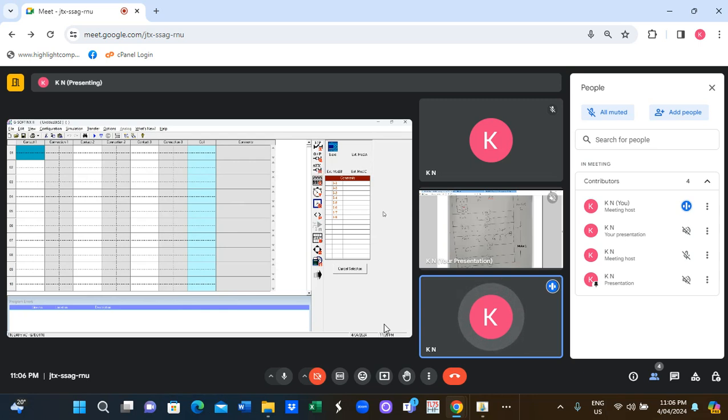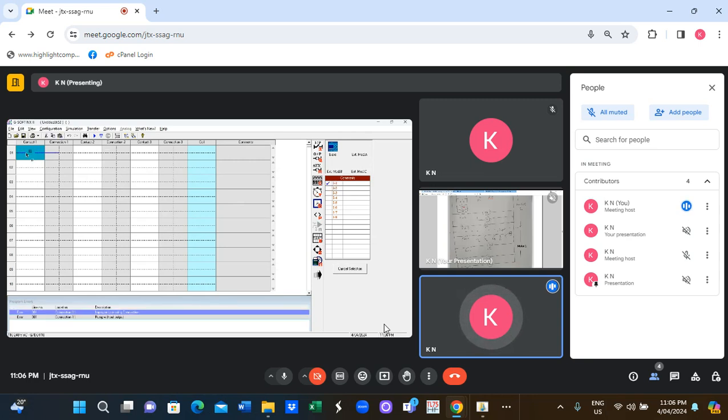So firstly I will put this on input. You press the input. Here I1 is a normally open contact to start the motor switch. I draw the wire and I insert it. So this is I1, you can see. I1 tells us it is normally open, so you can see the capital I1. This is normally open. Small i1 is normally closed. Now I put the I1.